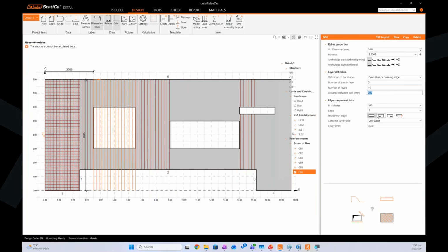So you can actually change the length here by clicking this part, H from the beginning, position 0, because you want to keep it here. Then for the length I just put 2 meters. Right, and because these are shear links, again I put the anchorage as a perfect bond. That's all for this one. We do the same for all these